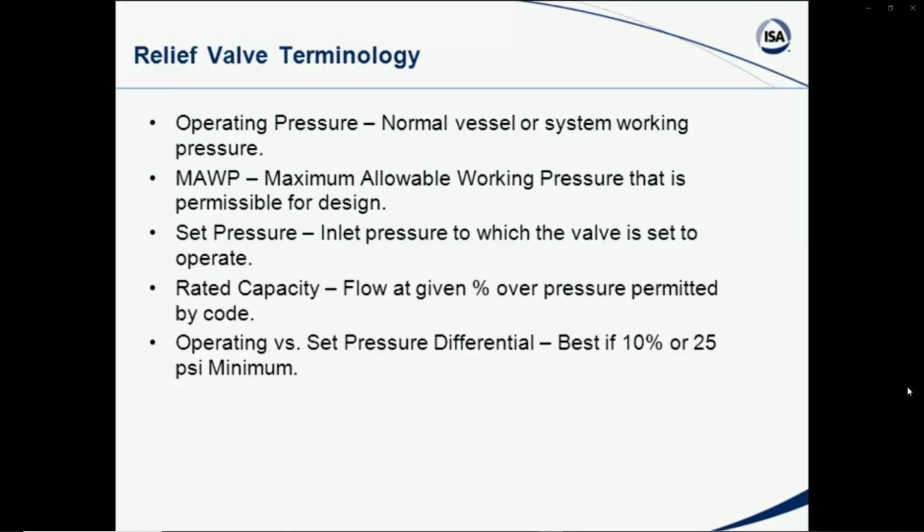Let's look at some relief valve terminology, and we'll get into an actual example in a minute. Operating pressure is the normal vessel or system working pressure. The maximum allowable working pressure means that if you have a system designed and set up, it could go up to this as a maximum working pressure. That's not a burst pressure, but a maximum allowable working pressure.